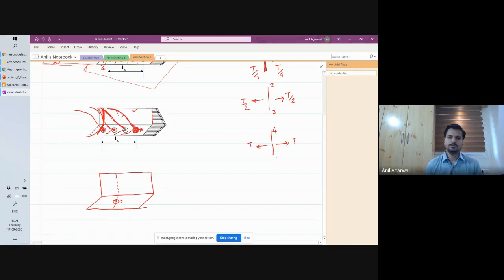So now the net section is here, and we know that at this point the entire force is still in this leg. The force has not been transferred to the other leg at all. So in that case, the shear lag effect, what is happening is that when the force is not transferred to the other leg, the entire force is carried by a single leg. That is what is called shear lag effect. And it will take some distance away from here in this direction before all this force gets uniformly distributed to both legs. Right? So that is the deal.